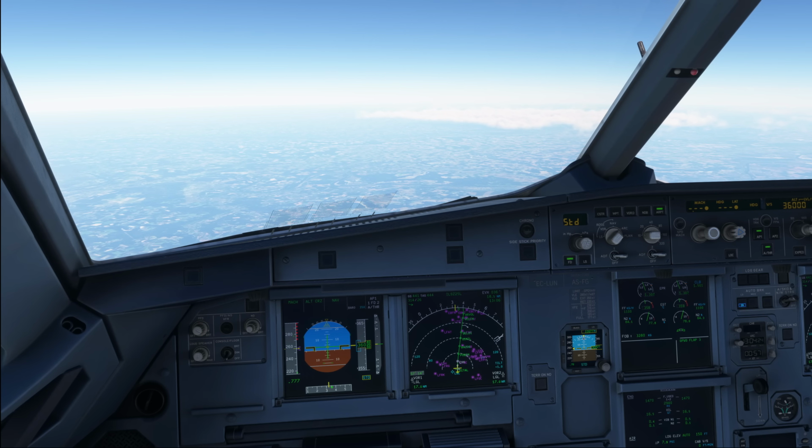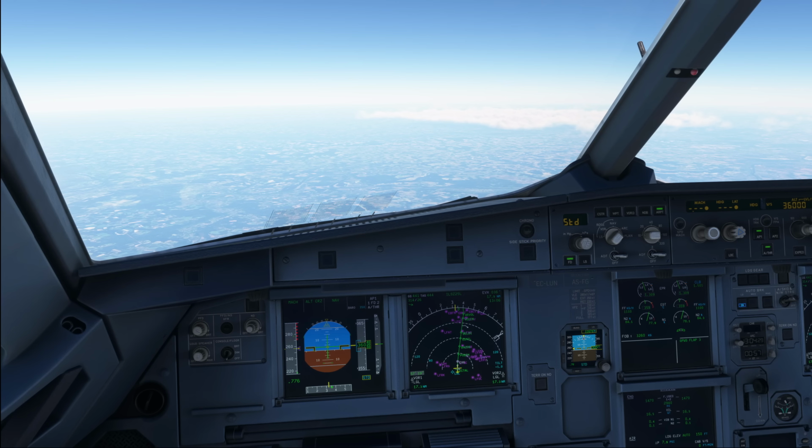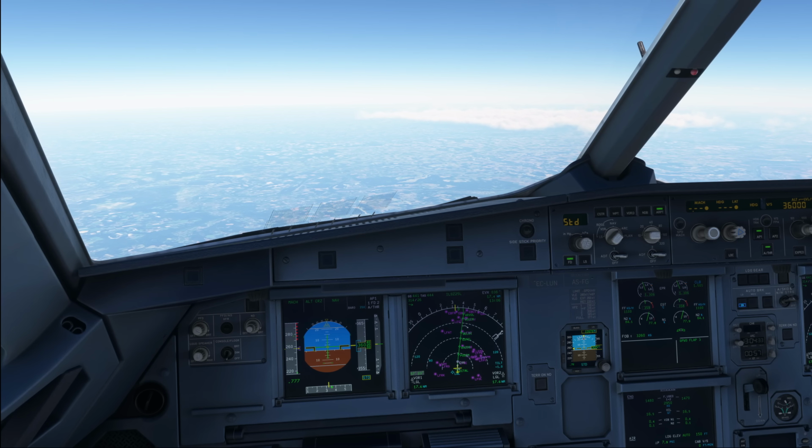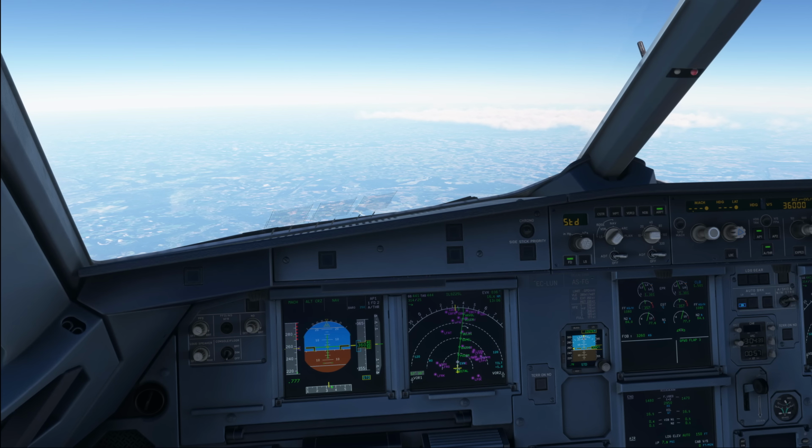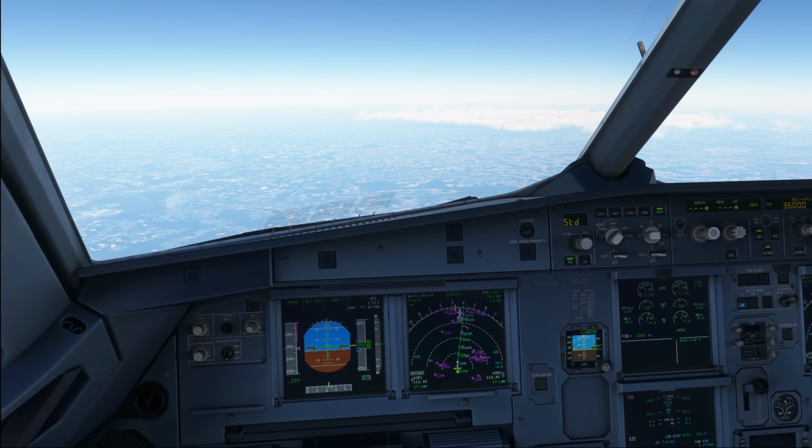Now, just to visualize that again, fuel consumption with bleeds from the engine and APU off is lowest. Fuel consumption with bleed from the APU and APU on is in the middle, and fuel consumption with bleed from the engines but the APU on is highest. So if you need the APU for takeoff, be sure to also use the APU bleed rather than engine bleed.